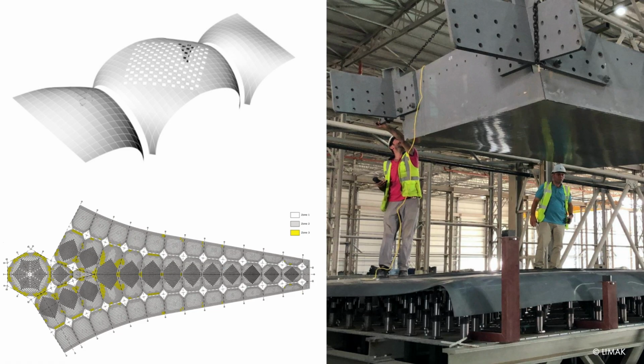The last challenge was to make the curvature of the panels, of the cassettes, possible. And 6,000 geometries once again, and this was possible in a collaboration between the general contractor Limak, as a structural engineer, and Adapa as a subcontractor. So only 85 molds have been required. The specificity of these molds is that they have hydraulic cylinders so that they can adjust to different geometries. And by doing that, the same mold can be reused up to 3 times in a day in order to produce the cassettes in a very, very quick way. So just within a year, all the 37,000 cassettes could be produced.